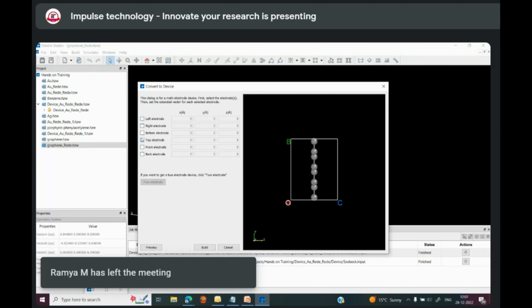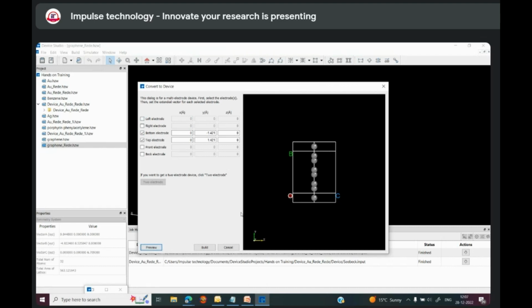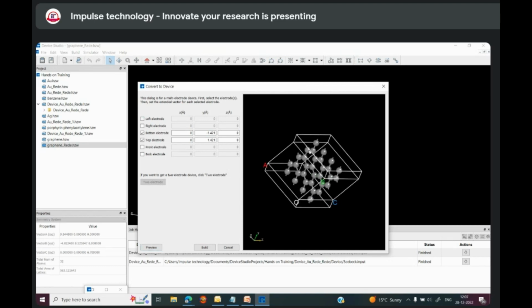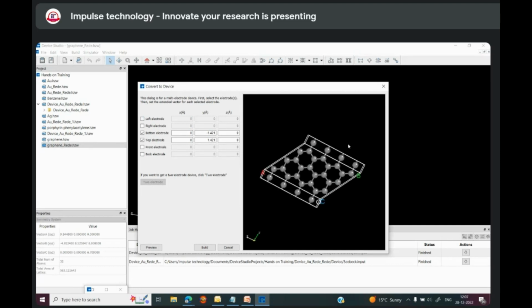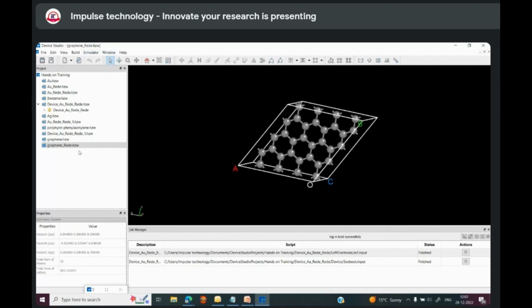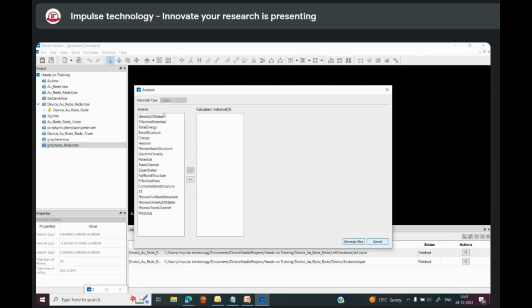Generally, people calculate the Seebeck coefficient in 2D materials, for a monolayer, not for a device part, but now you convert it into a device. In the simulator NanoDCAL analysis part, the Seebeck coefficient is not there for the crystal part. Okay, go for the ZT one.